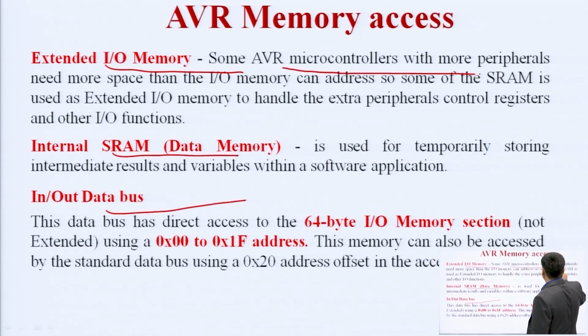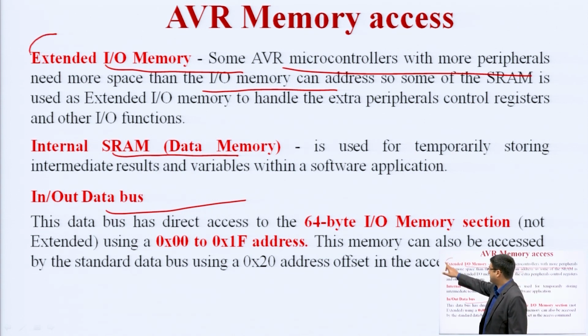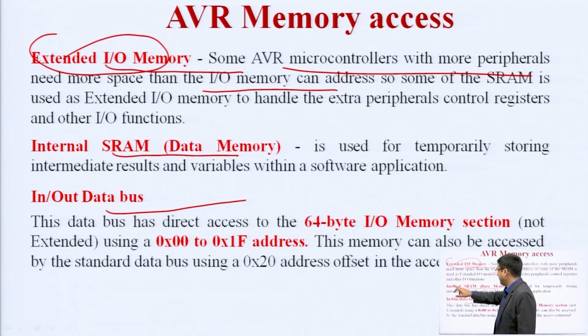Some AVR microcontrollers with more peripherals need more space, so to handle the input output instructions, we need an extended input output memory. One of the important features of the AVR microcontroller is that it has an extendable input output memory. It also has an internal RAM.